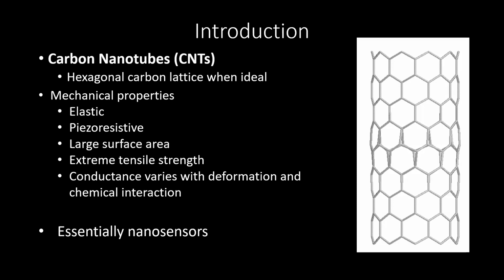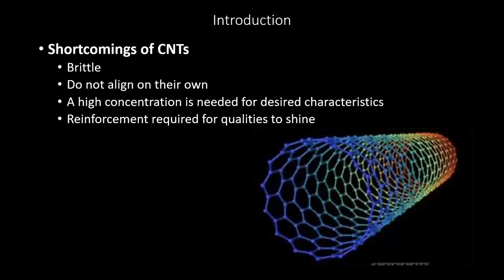They can also be arranged into large surface areas with even distribution, imbuing their characteristics onto large structures. They have great tensile strength, practically an engineer's dream, as they are almost impossible to break in tension. These qualities work in tandem to make them into inherent sensors. In the paper, the method of measuring their internal electric characteristics as they deform will be used to indirectly measure their deformation.